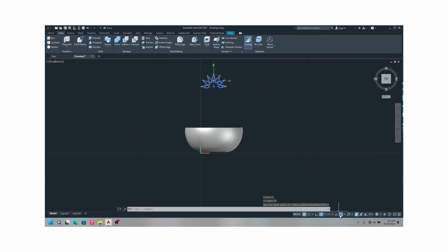And it's probably best to turn off ortho when you're moving this around on your own, since ortho will try to snap to the nearest one. So here just turn off ortho in case you're having some problems with actually moving the object.